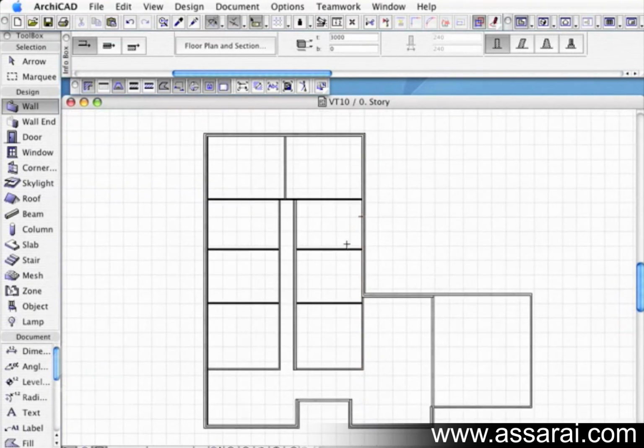So there's a couple of different ways of employing different techniques that we've gone through during these wall movies, and you'll find that you can use these same techniques for most of the elements throughout your ArchiCAD project. Now that we've gone through placing walls, editing walls and changing wall constructions, I think it'd be a good idea to create your own little house as an exercise and just practice those multiply functions, change wall functions, injecting properties, editing, transferring properties, and by actually creating your own house, it's a good way to practice all these techniques that we've just learnt.